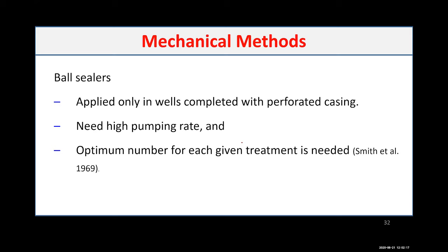There are ball sealers, which again are applied for the perforation part, but in addition to the mechanical aspect, they need a higher rate. Ball sealers need a higher rate to be pumped. So you cannot pump ball sealers at a low rate. They will not sit in the perforation.